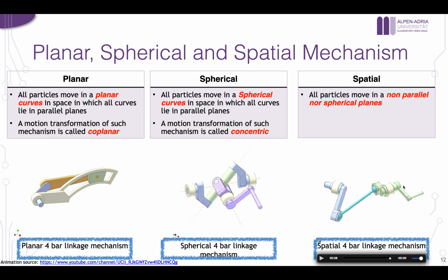If I apply a motion there, then this motion would move through this link, which is the source link, then to this link, then this link, then it will come back to the frame. So that is why it's a closed loop. It starts here, then the frame, and so on, and the frame. So there's no free link at the end.